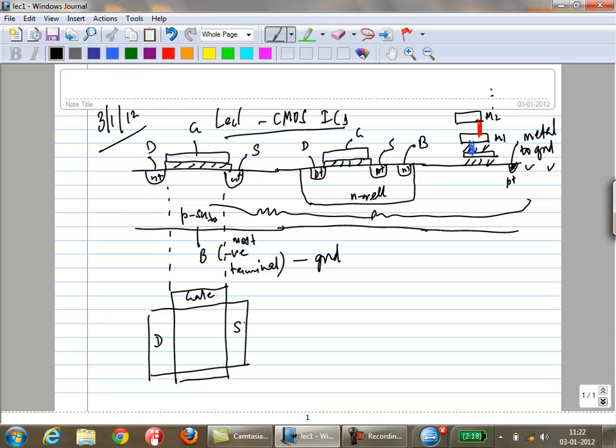You're just looking at the top view; this is the side view of the NMOS. You have the drain, the source, and the gate. Okay, where do you have the bulk? So in reality, let's put in a P plus. Let's say you have a P plus connection to ground, even for this MOSFET. Okay, so you would have bulk contacts here.